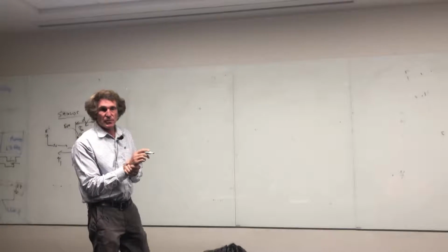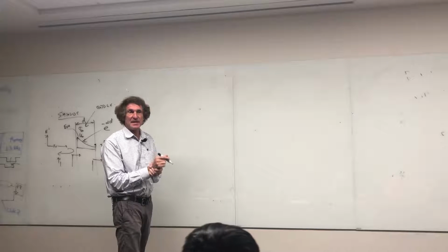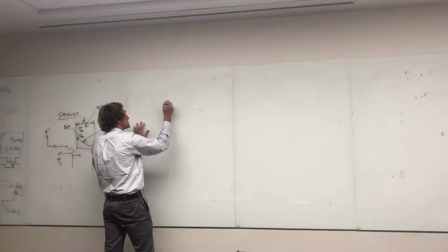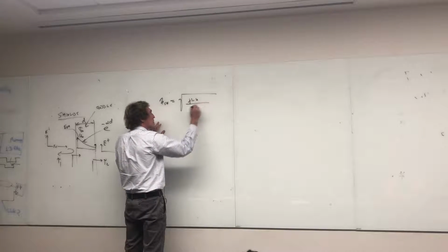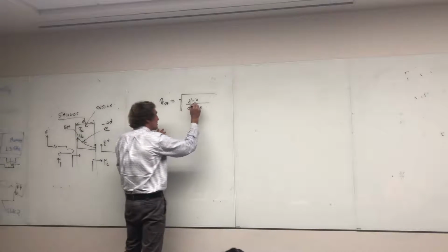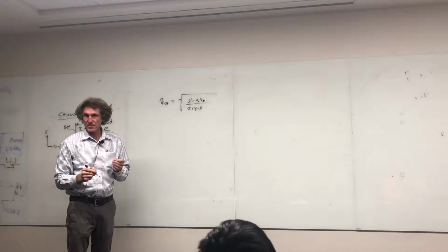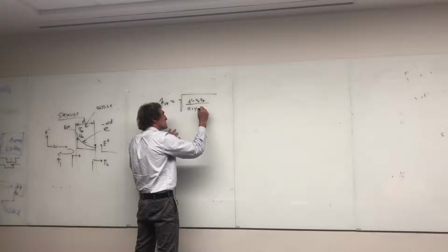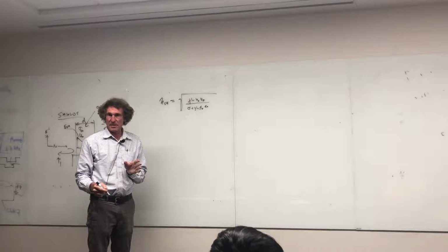Now I'm going to just try to talk you through all this to make sure everybody's clear about all these steps. These shield problems are very easy, but unfortunately it's very easy to mix something up. So the first thing you always do with a shielding problem is find out what the actual intrinsic impedance of the shield is. So for the shield, the standard form is the square root of j omega mu over sigma plus j omega epsilon. Now mu is mu naught times mu relative, so I'm going to put that in there because a lot of people forget there's a mu relative, and when it's steel, steel has a mu relative of about 1,000. It's not 1. Everybody understand that? Usually this term right here, omega epsilon, is about 0 compared to the value of sigma.